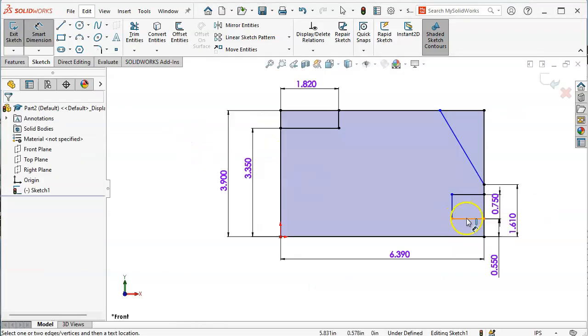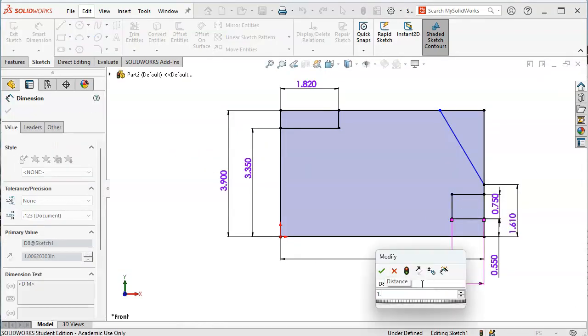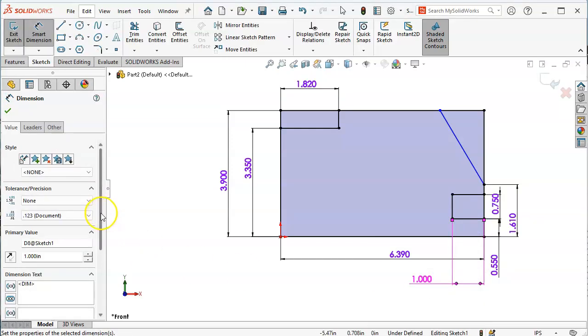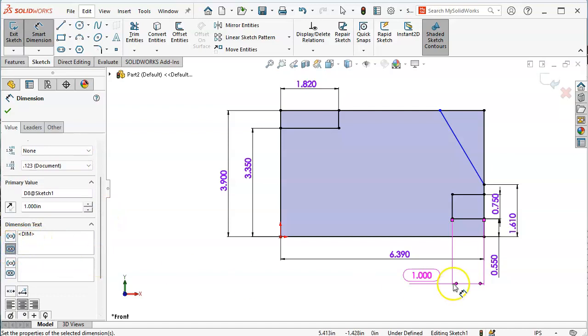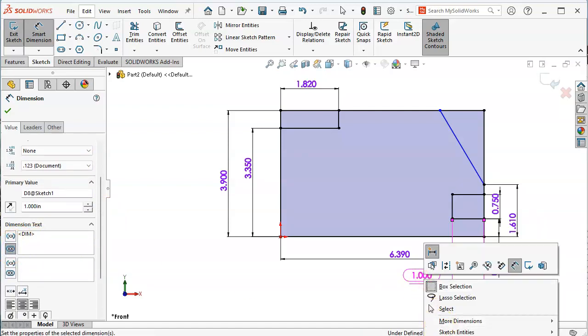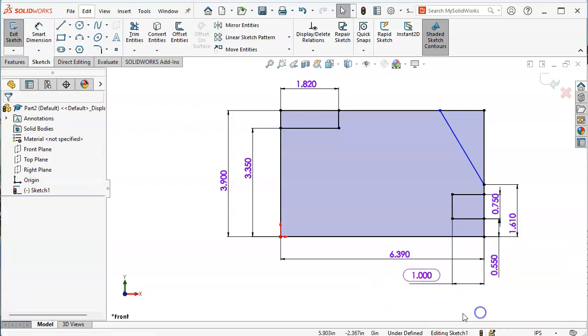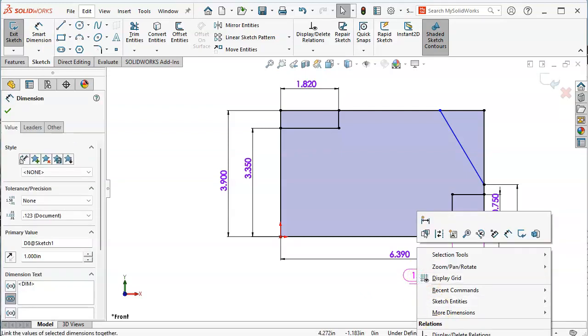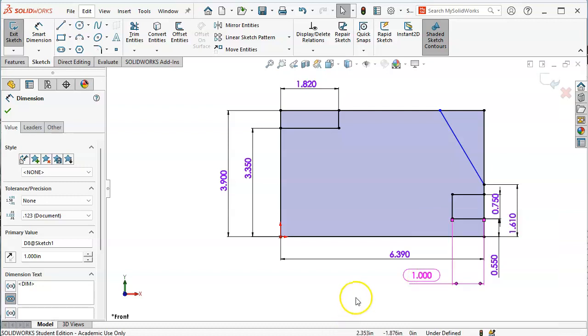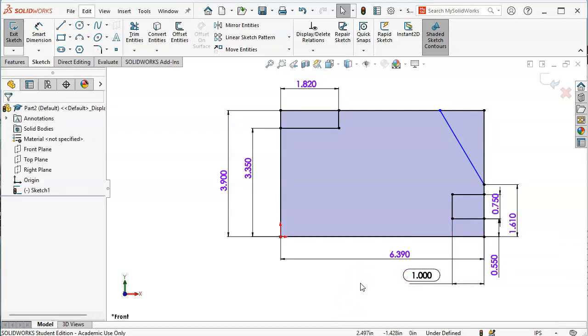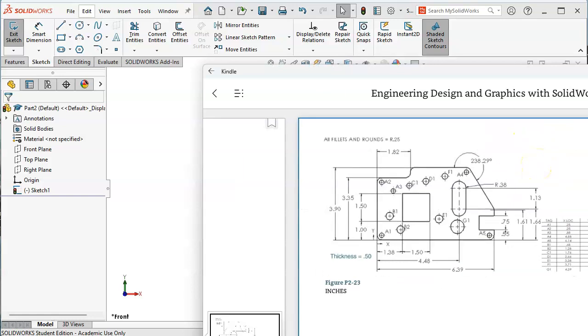Again, if there's a missing dimension you can't find, don't spend a lot of time messing with it. We have the tools. I'm going to set it to be an inspection, and then I'll mark it for the drawing. So let's go back into select. Mark for drawing is just off of the screen that I'm using. So it highlights it, it notes it. If I insert, I don't insert dimensions very often, but if I set myself kind of a reminder, that would be a dimension that comes in and needs to be resolved.